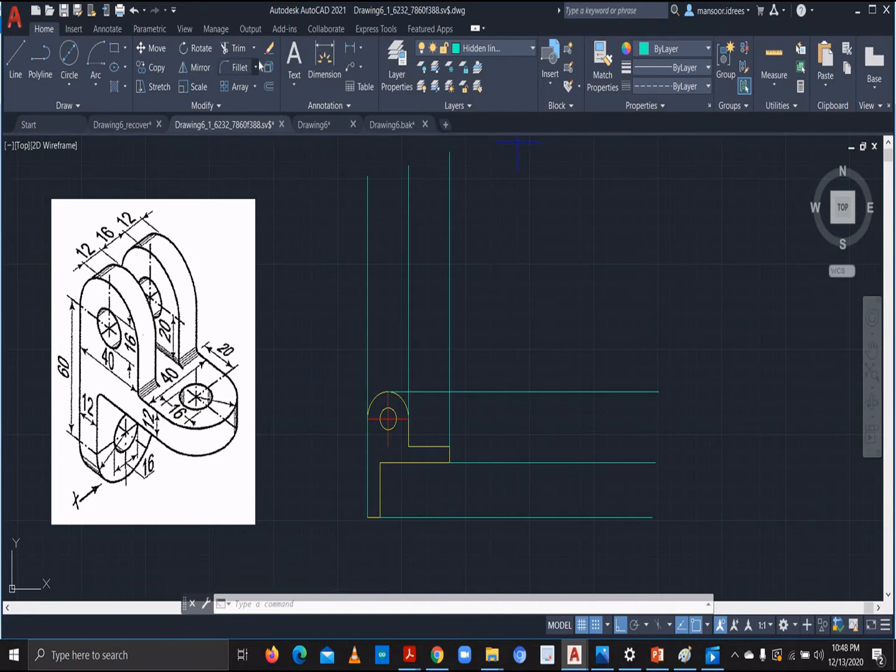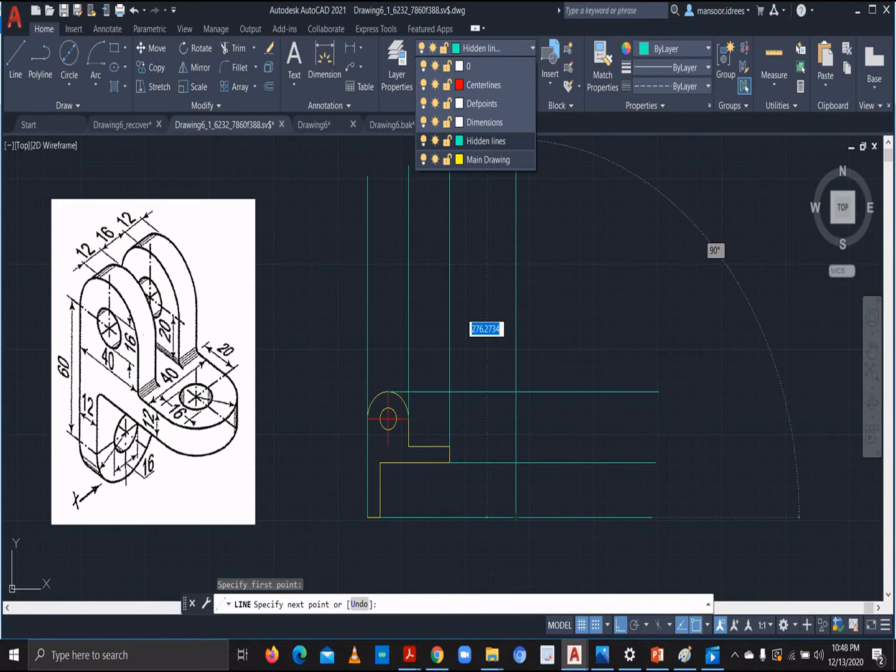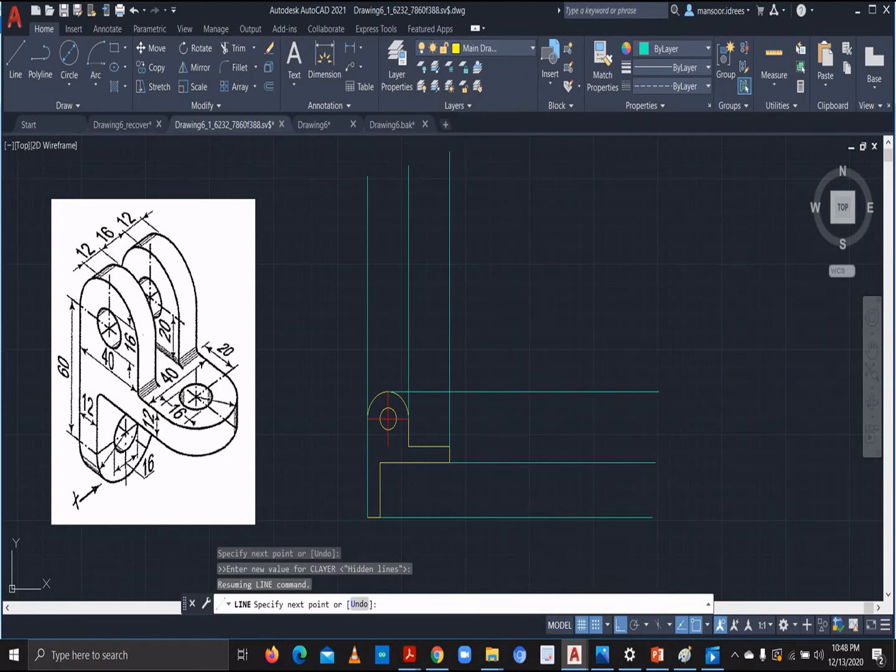So now I should make the side view. In the side view, we'll see these two legs and this part and the bottom part. So let's begin. This width would be 40. Sorry. So I'll take from here. I have to change the layer first. Again, I'll take the line command and go 40 over here. And let's just finish this.